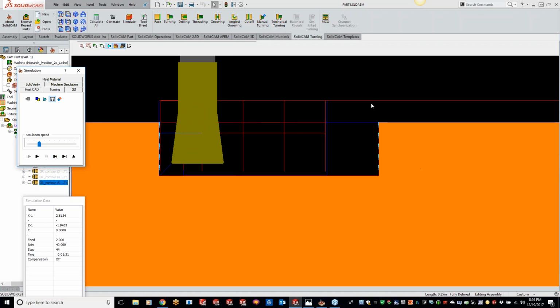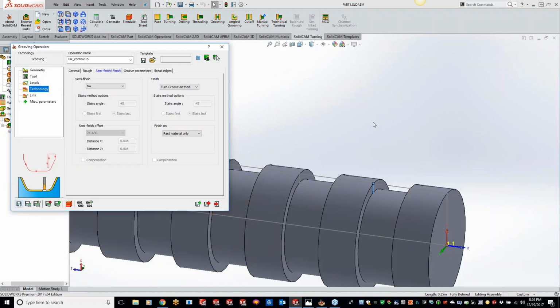Kind of keeps that cutter cutting down instead of coming up the faces, which would put a lot of pressure on that tip, kind of going down in. So this way, hopefully everybody was able to catch that. It comes down right here, then moves over, finishes up there, stops, comes up, and then comes down, doing a straight clean finish into there. So that's one strategy that we have here.